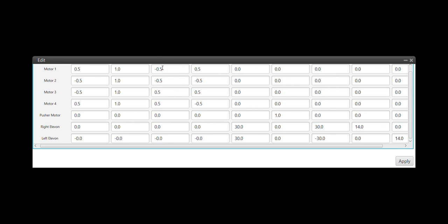It will be the same, for example, for the roll in multicopter mode, in which if we want to roll positive, so roll towards the right, we will decrease the action of the motors on the right, the first one and the second one, and we will increase the action of the motors on the left. And the same will work for the pitch in multicopter mode, the yaw in multicopter mode, but also for the thrust and pitch, roll, and yaw control for the fixed wing mode.